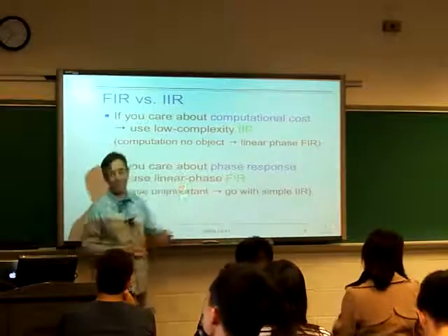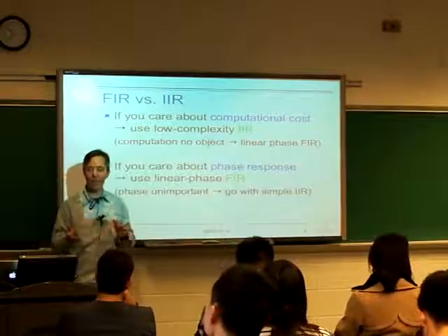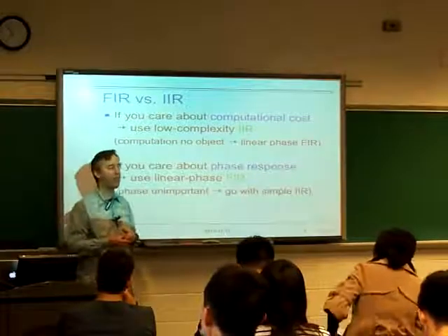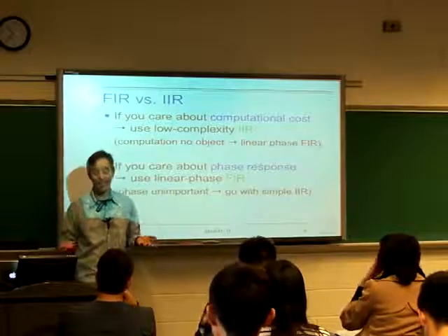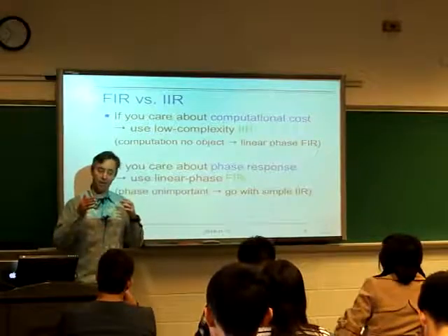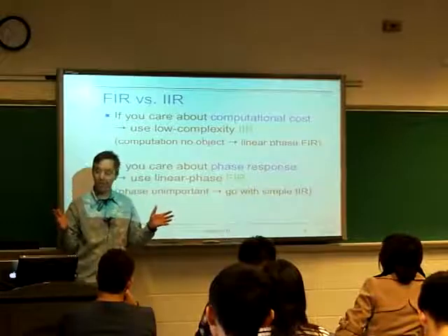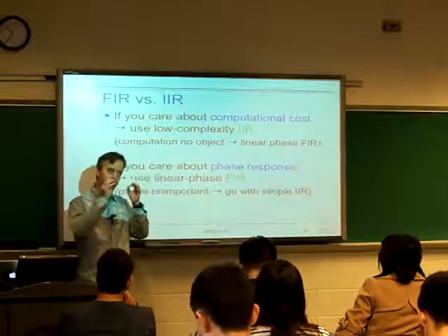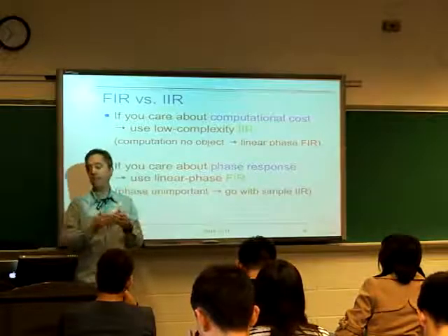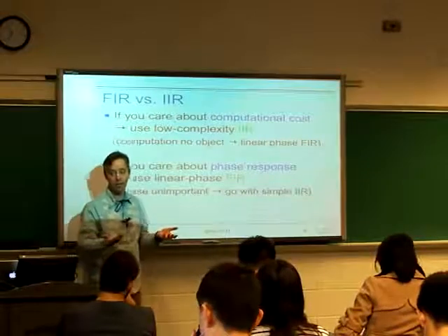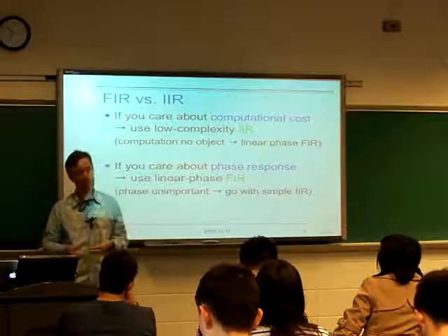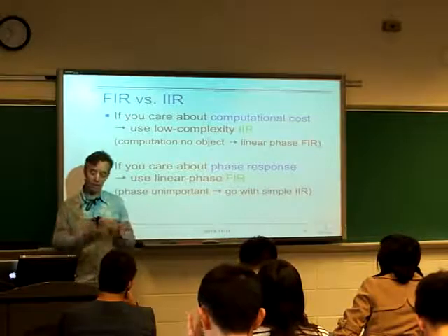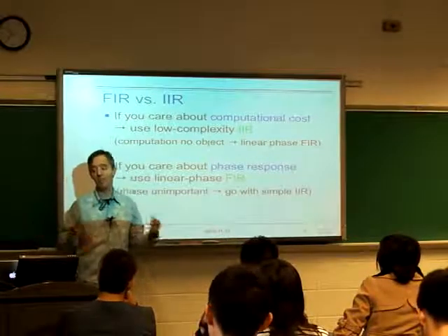So yes, there are certainly things you can do which can try and fix up the phase, but actually it's a lot of work. I've never really done it, and certainly it's not like you can just control it arbitrarily. It's like, okay, here I'm going to try and control the phase at just a few frequencies, and you can see what you can do. Whereas with a linear phase filter, it's so nice, right? It's like, okay, there is no phase issue. There's maybe some delay. There's no relative phase, and so it's a lot more attractive.